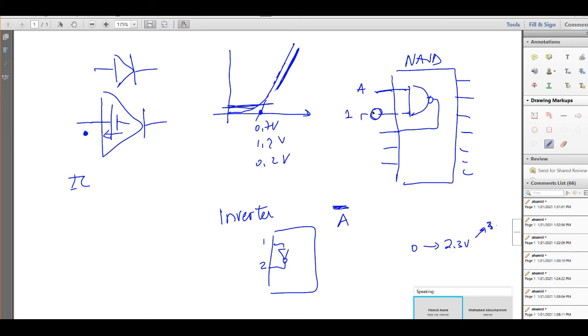If we keep this one floating like that, this will be working as AND gate, not inverted gate. You'll be having A and B bar in this side. But if you need to avoid having this situation and work with NAND gate as inverted logic gate, you have absolutely to force this one to be 0 logic all the time. So you connect this one to ground. So by connecting this to ground, I'll be sure that I have all the time A bar this side. This will not affect my circuit.